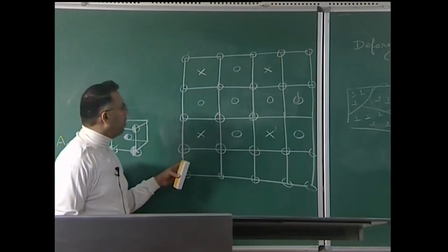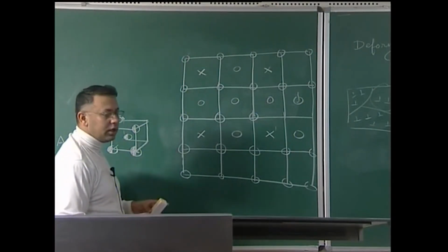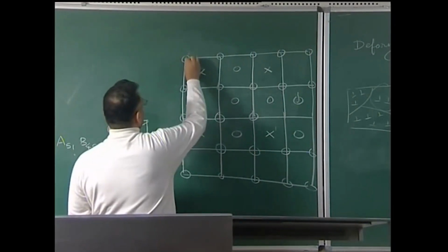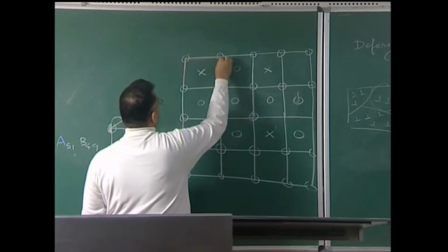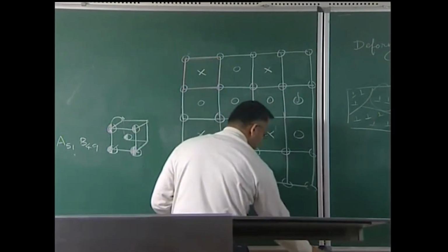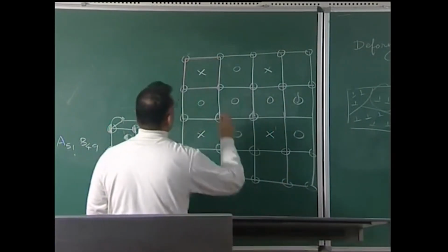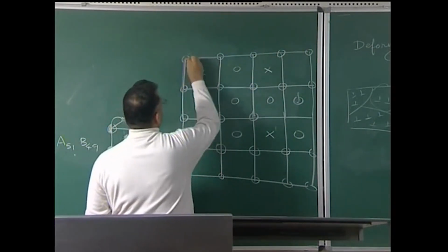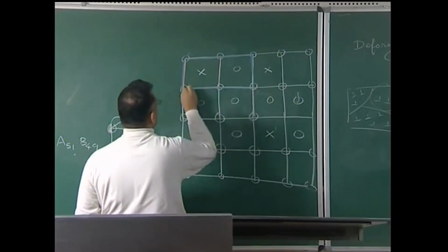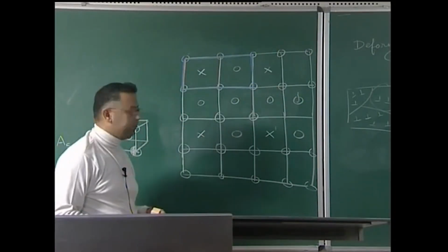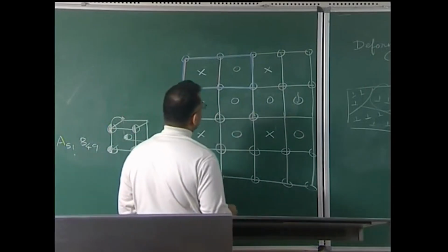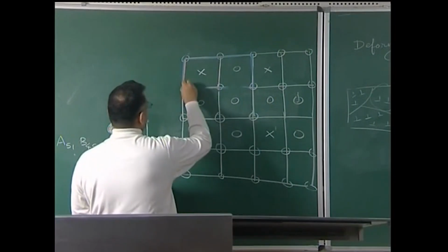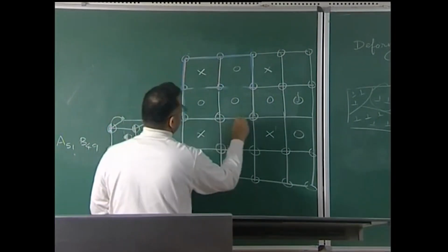Now, this is what we call a vacancy ordered phase. See that my original unit in the crystal would have been a small unit cell like this. Now, when the vacancies get ordered, you can see that my unit cell has expanded, and this whole big region is my unit cell. Sorry, this is not my unit cell, let me correctly draw the unit cell. This is my unit cell.